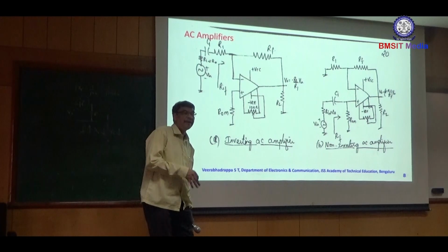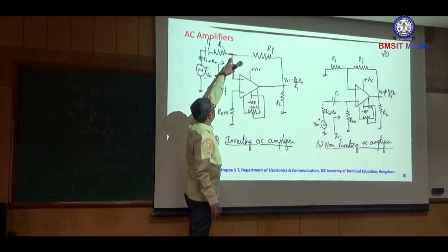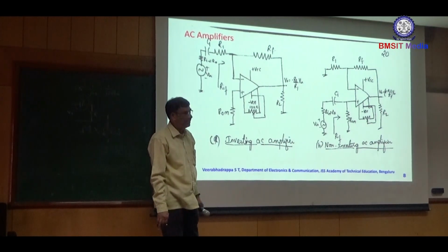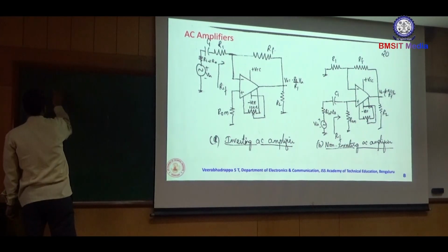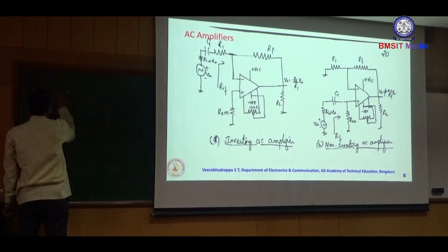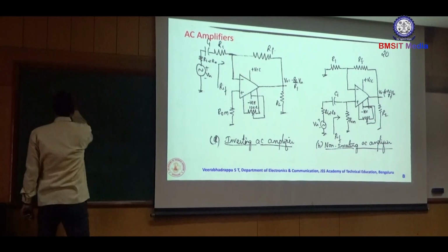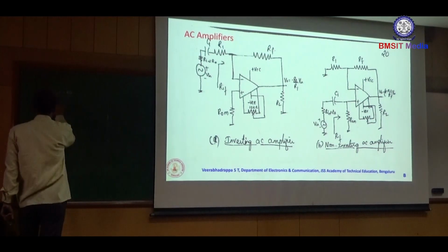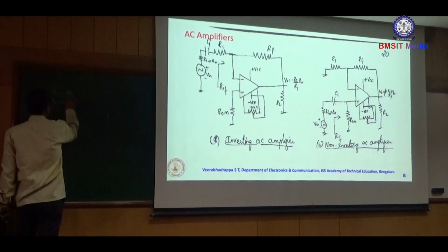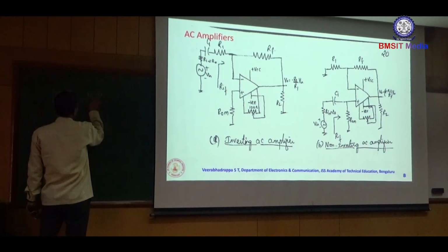Up to what point, that question arises next. To analyze this, I am applying KCL at this node A, the inverting terminal. KCL at node A, then you are going to get Vin minus 0 divided by, because this is virtually grounded, directly I'll take 0, or if you want you can write VA, divided by Ri plus R1 minus J XC, equal to VA minus V0 by Rf.